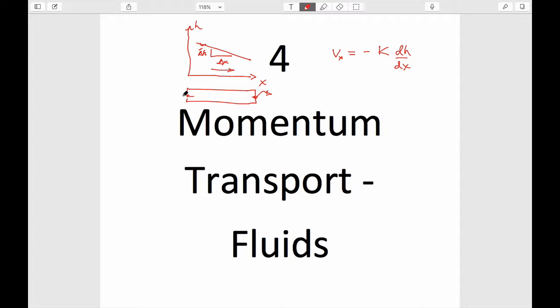And so that's how we were able to develop this conductance matrix, which if we look back on it now, basically allowed us to say that flow rates were related to nodal values of heads through a conductance matrix, and that conductance matrix actually did conform, as we could show now, as something that looks like this, which we've seen many times also. Right? And so that was our simplification in dealing with this.